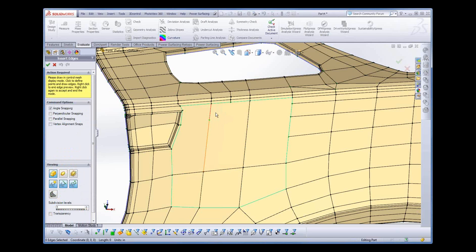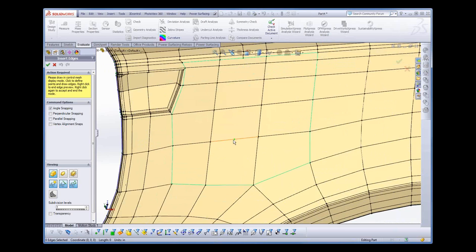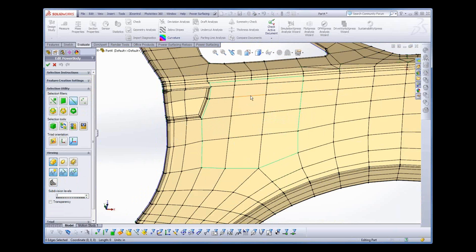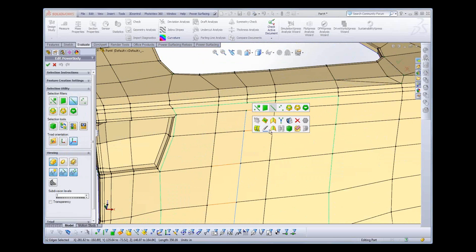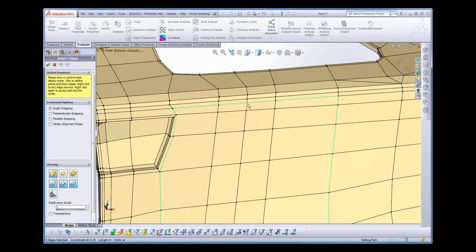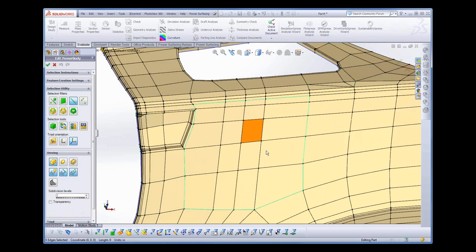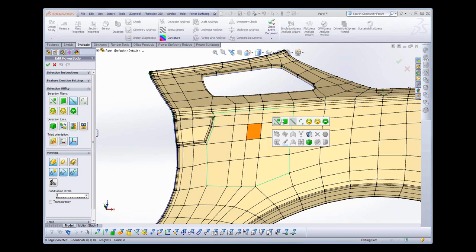Here up to here, and this one over to here. There. And you can see I've got a little bit of a problem here in that the edges don't match up. So I'm going to switch over to Edge, select an edge ring and insert an edge, right-click to say OK, and I've got one more little piece here I need to manually connect with my Insert Edges tool. Then I can select my new faces that still are not smooth and continuous with the rest.